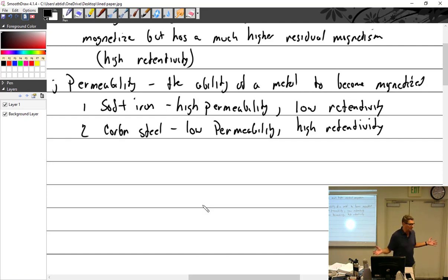When you take away the magnetizing force, if you put these iron filings in there, they would be attracted to a crack, but as soon as you turn off the machine, there's no more flux leakage and the filings would just fall right off. So you have to actually magnetize it. You have to have the current running while you put the stuff on, and then you can look at it. It'll stick at that point unless you start messing with it. Carbon steel, you can actually put the current on, then apply the stuff. And you can wipe it off and apply it again, and wipe it off, apply it again, because it's just going to be that way until you get rid of the magnetism.